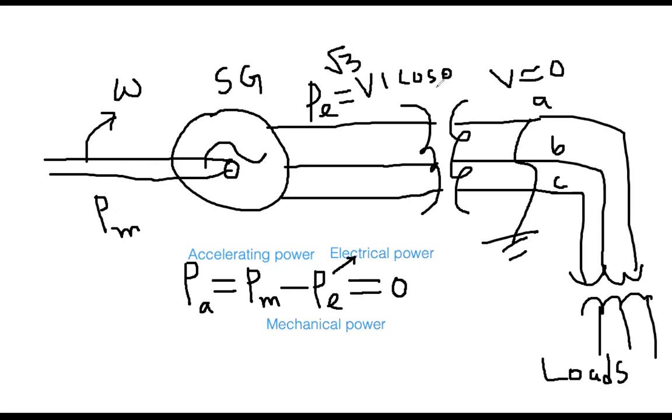Whatever the power factor was, the voltage here becomes almost 0 or exactly 0. Consequently, on the primary side, that will also be 0, whatever the number of turns. Ultimately, your electrical output power Pe will be close to 0, or at least a very, very low value.